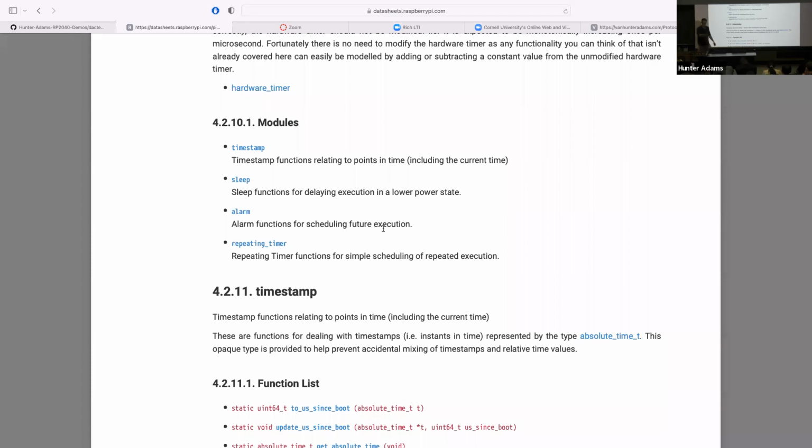The SDK abstracts that low-level capability of being able to write to the alarm register to schedule execution for some function in an interrupt service routine in the hardware interface library to the timer. That's your lowest level interface to the timer that isn't writing registers directly by yourself, right? It is a series of functions that abstracts the manipulation of those registers directly.